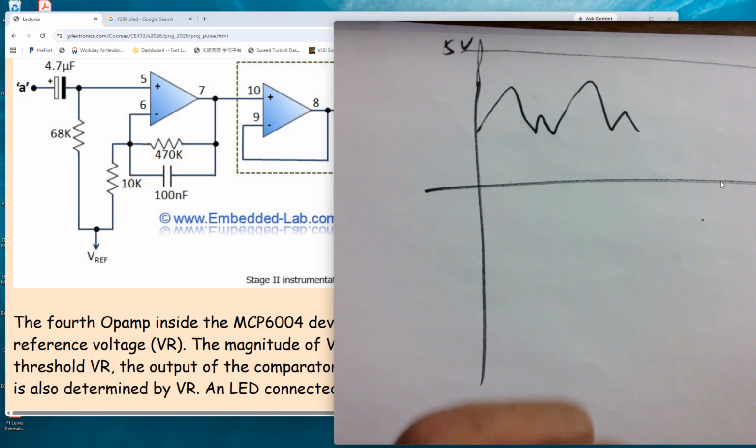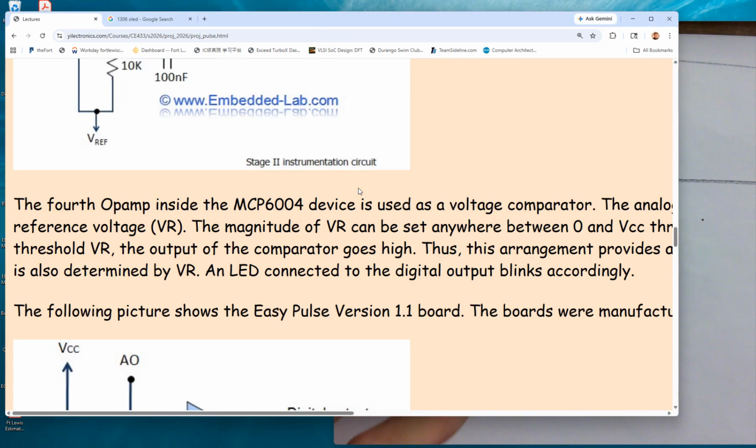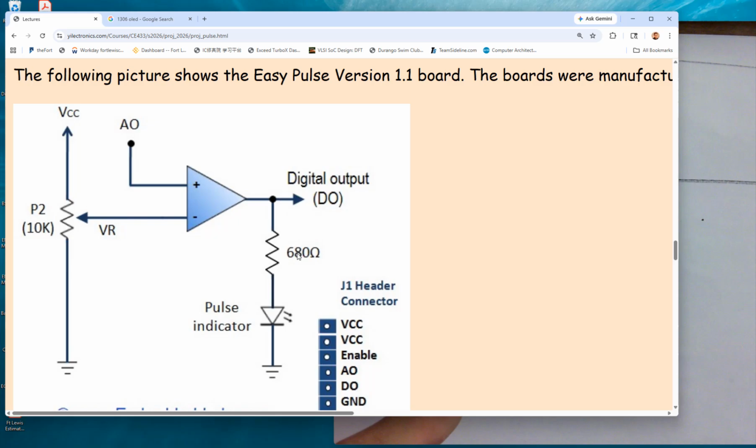First, it's always on, right? Second, it's sometimes getting brighter, sometimes getting lower, right? It's not showing an on off. It's just dimmer, brighter like that, which is not ideal. So that's why we want to see the beats. So we connect the signal to a comparator in order to see that on off signal.